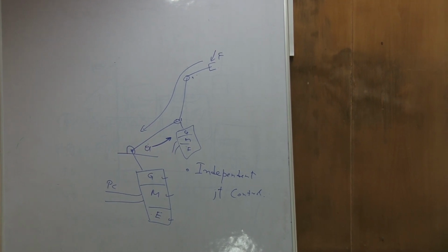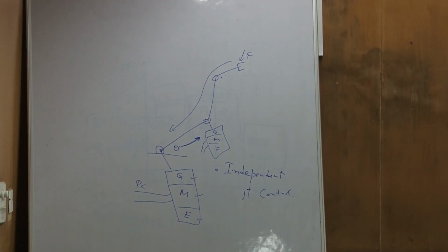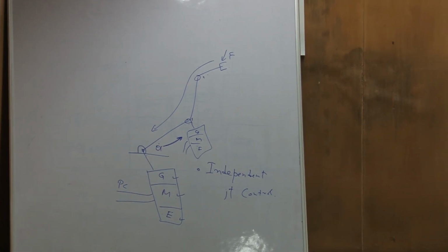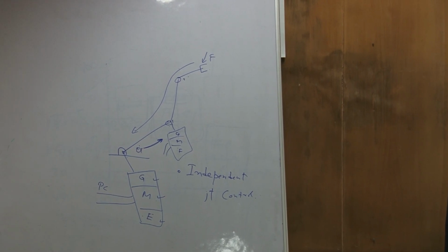So internal sensor is required for the basic working of the system, like position, velocity, acceleration. And then there are, so without these internal sensors, the robot cannot work. Without internal sensor, it cannot work. Now there are also sensors which are external sensors. For example, there can be a force torque sensor there. There can be a camera mounted there. Now these are external sensors. So external sensors are required for interaction with the environment. For example, vision, force torque, other. Now if some of this goes bad, the robot will not die, but it will still work, but the interaction with the environment will come down.